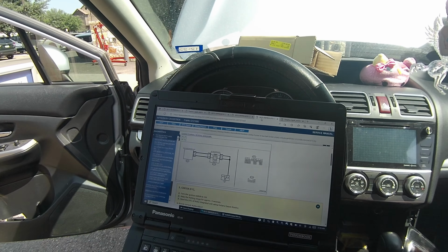Let's go ahead and abandon the simplified wiring diagram and let's go find a more complete wiring diagram and see what's going on. Shift lock. Hey, look at that. Shift lock control system has its own circuit diagram. I can work with that. So now I just want to go over some components that I see here. I like to identify. When I get one of these diagrams, I don't want to jump to anything right away, but I like to just identify what I see.